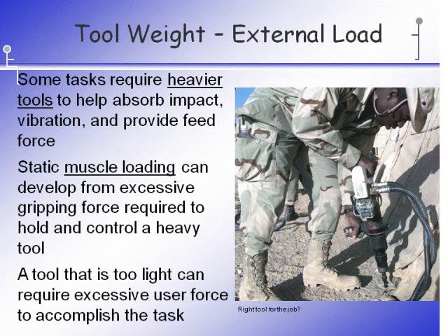Some tasks just simply require a heavier tool, such as this gentleman using this drill. He really should be using a longer handle drill, so he wouldn't be in this particular orientation, but this is probably the best drill that he can get. The tool is really heavy because you need the weight of the tool to be able to drive through the medium in which he's trying to push through. Here you can see he's got two handles on the tool. He should be holding the tool like a pistol grip tool instead of being bent over quite so far.